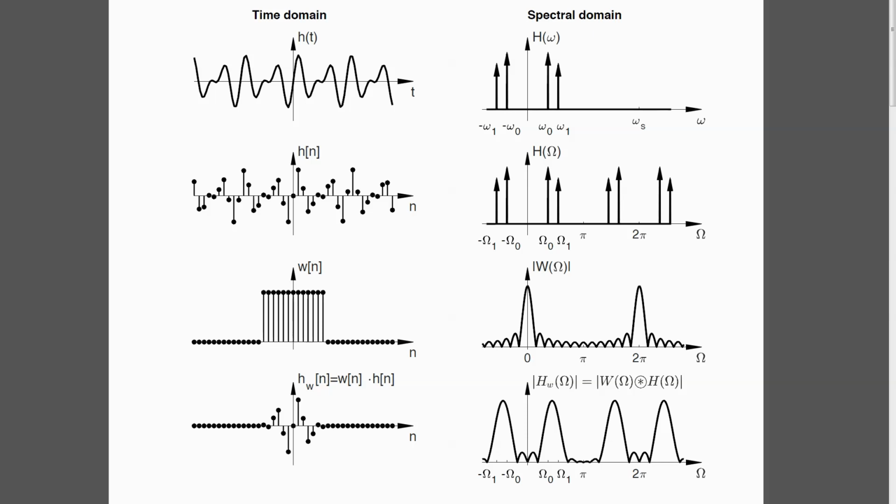Now, what can we do to improve our spectral resolution? Well, our problem is that this peak is too wide. And how can we make it more narrow? We had this previously. This peak will become more narrow when this window will become wider. Let's check it out.